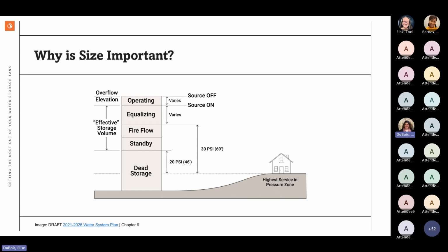But that doesn't always happen because the critical elevation in any tank is that overflow elevation that you're seeing. Because of that overflow elevation being what it is, and especially on the elevateds, having standard head heights on the bowl, which makes them cheaper. That's the difference between the overflow and the bottom of the bowl. We may not be able to get you to 10% or less without adjusting that overflow or costing you a lot of money.